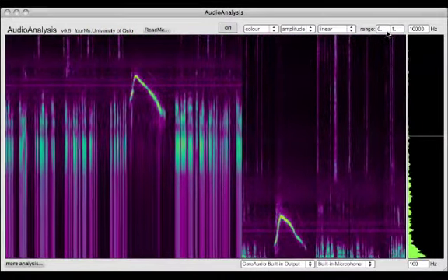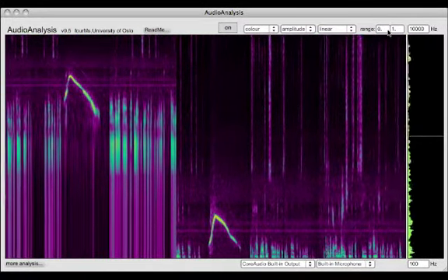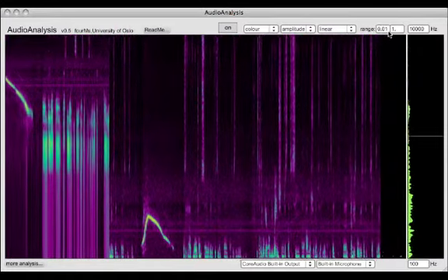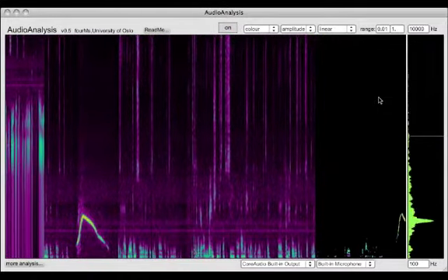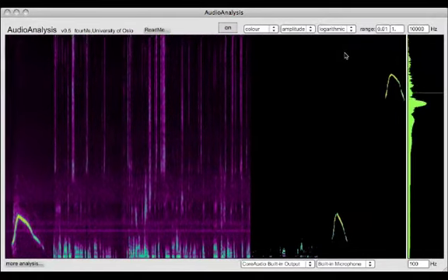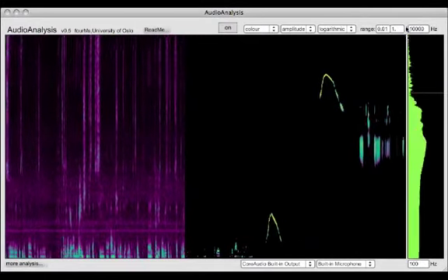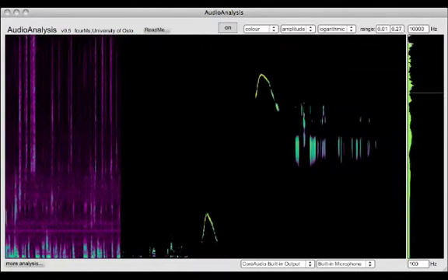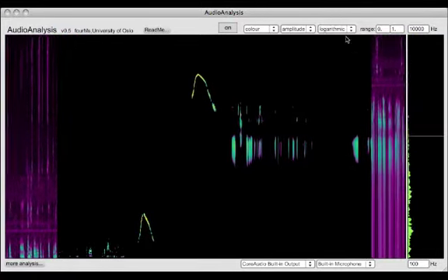It's possible to go here on the range and adjust that to see how much of the amplitude that you will actually display. It can be useful to set the range a little bit higher. You can click and drag here, and then you will actually filter out also some of the background noise, as you will see here, or if I change to logarithmic. That will also then remove most of the other noise components. You can also change this down a bit here on the right side to show all the parts of the spectrum. Or you can go back to show the whole range again.